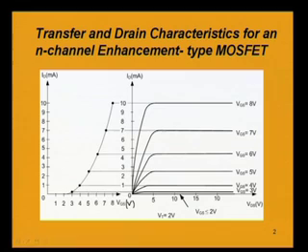Obviously, the earlier point is 0 current at 2 volt, because for VGS 2 volt, which is the threshold voltage, the drain current is 0. So, 2 volt and 0 milliampere drain current is one point actually. The curve will start from this point and it will continue.